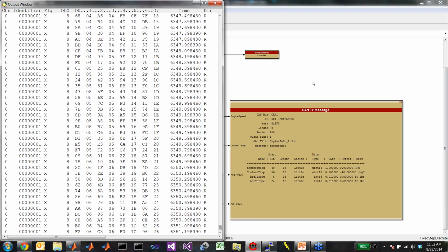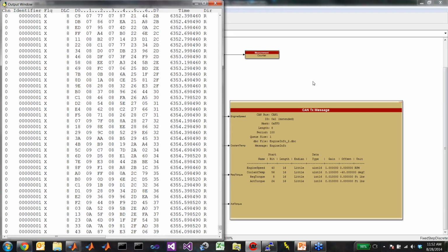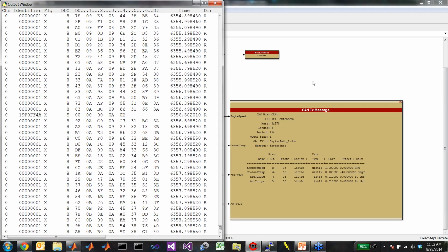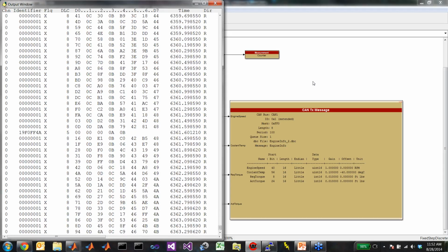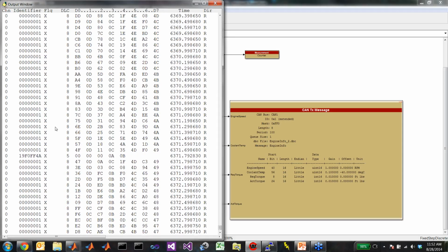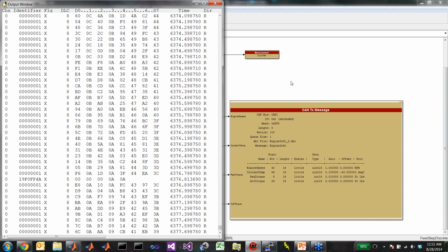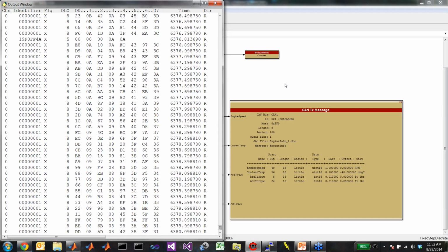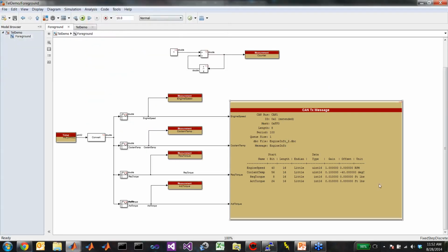So what you're saying is that message, the 19F0FF4A, may be useful for other modules in the system to monitor, to know details about the telematics. Can you show how you set up that CAN message in the model? Yeah. And to answer your first question, yes, the intent of that message, the 19F0FF4A, is to be used by a display so that you can show the user if an update is in progress, or whatever your display needs may be.